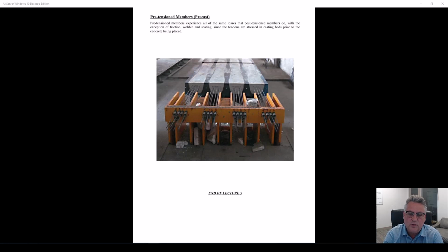The computer will tell you that a flexural stress is not working at some point in the beam or slab, and the young person who's never had this class will put more tendons in, just start upping the force in the computer until the computer says it all works, because we have a more cowbell philosophy. Your homework number 3 is designed to get you to think in terms of less cowbell.